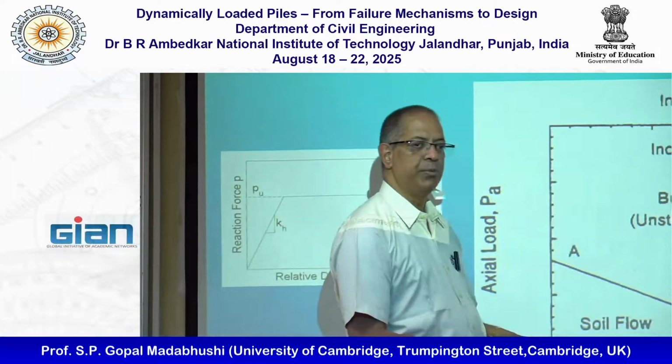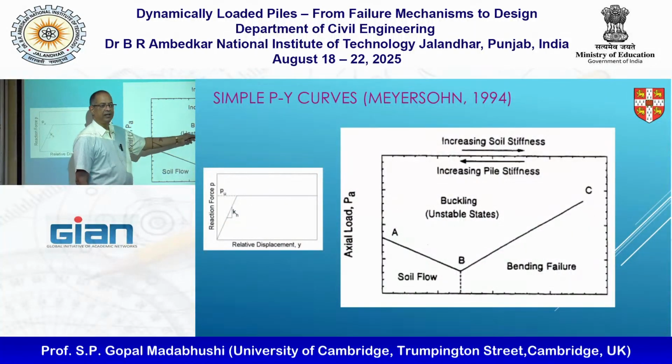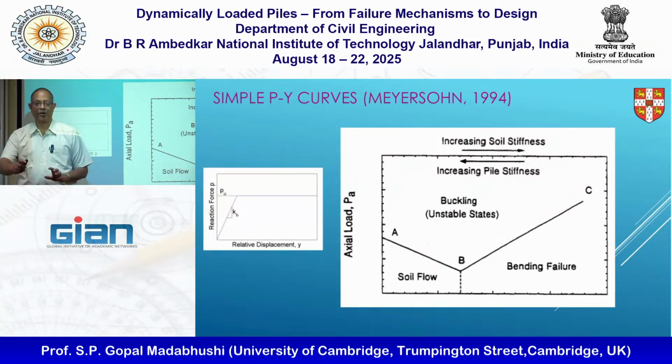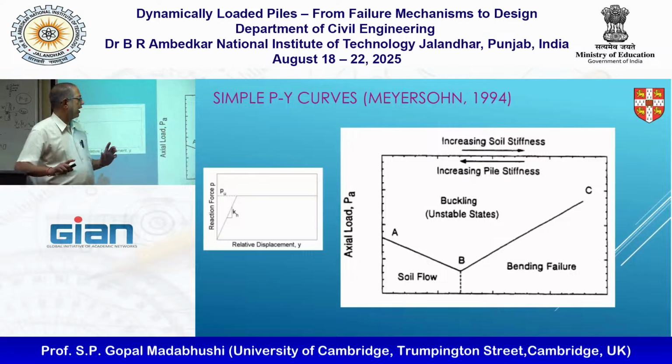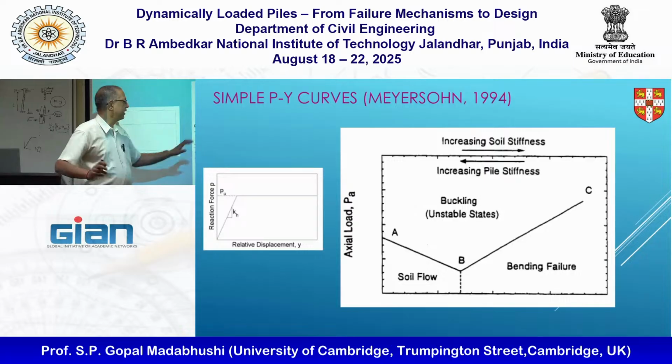And the most important thing is, these are all unstable states. Buckling is, as I keep banging on, the instability that is the killer. That means you can't predict when it will fail. It will fail suddenly on you. So it is an unstable state.